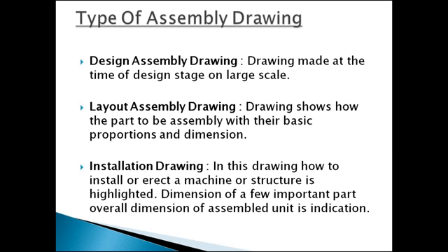So the cost may increase because tight tolerances are a big thing. If the tolerance is very low, or a very super finish is required for your component, the cost of manufacturing is going to increase. If the cost of manufacturing increases, that directly affects the cost of your product. That's why we need to take care of everything while designing an assembly drawing.